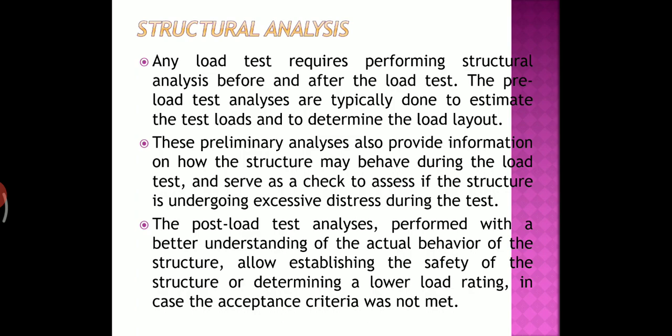Then structural analyses are to be carried out before and after doing the test. So these are all things that are to be done essentially, because any load test requires performing structural analysis before and after the load test. The pre-load test analyses are typically done to estimate the test loads and to determine the load layout.